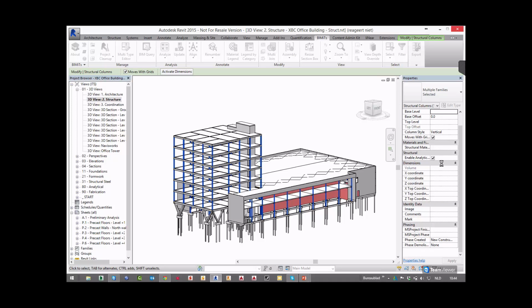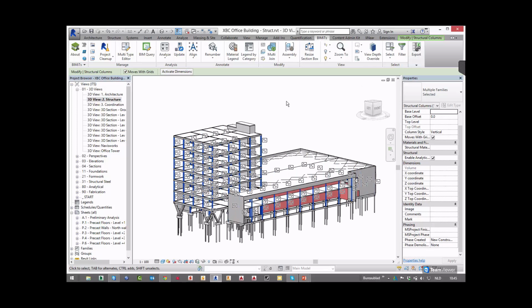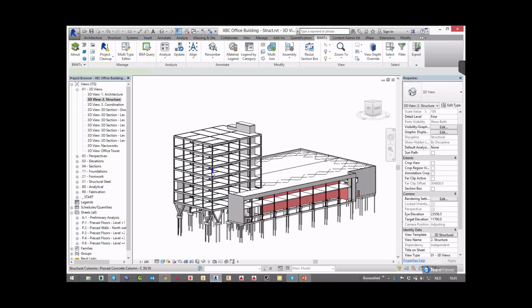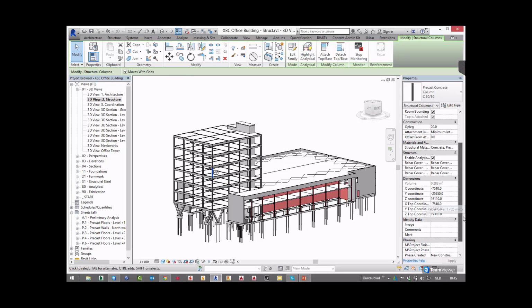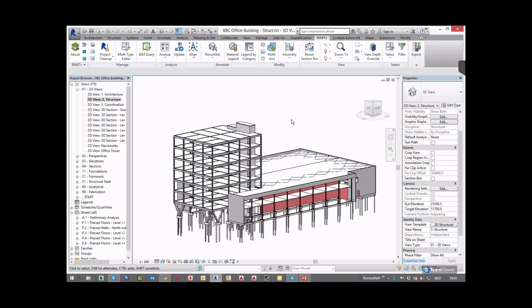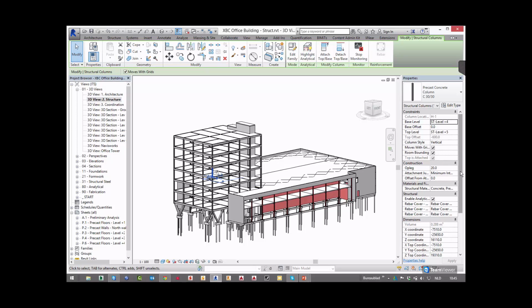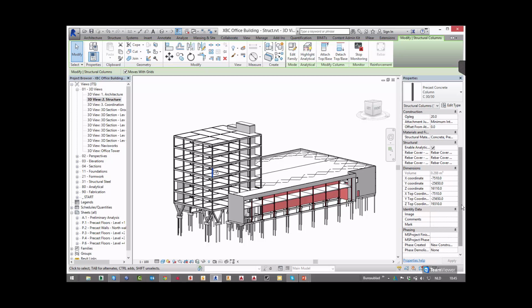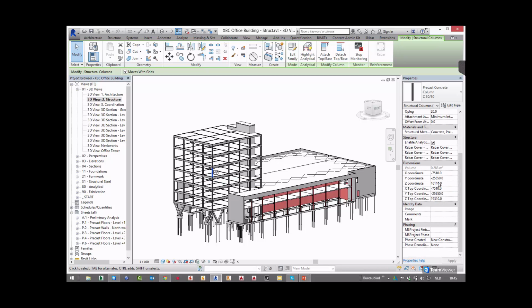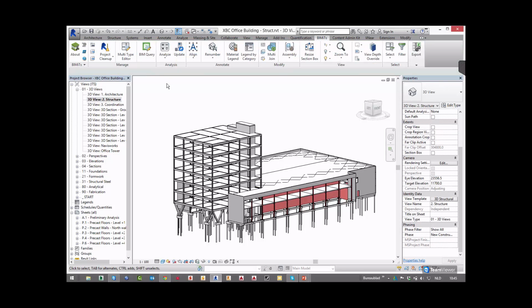And then I'm going to use the Bim Query Tool. So the Bim Query Tool is a kind of Excel format in Revit. So you'll see all the X, Y, and Z coordinates are filled in. And I want to add a mark to all my columns based on, for example, the column location mark. For example, I'm going to use the Z coordinate. So I want to see a mark that's filled in H1 with, for example, the Z coordinate. This is an example I'm going to give.